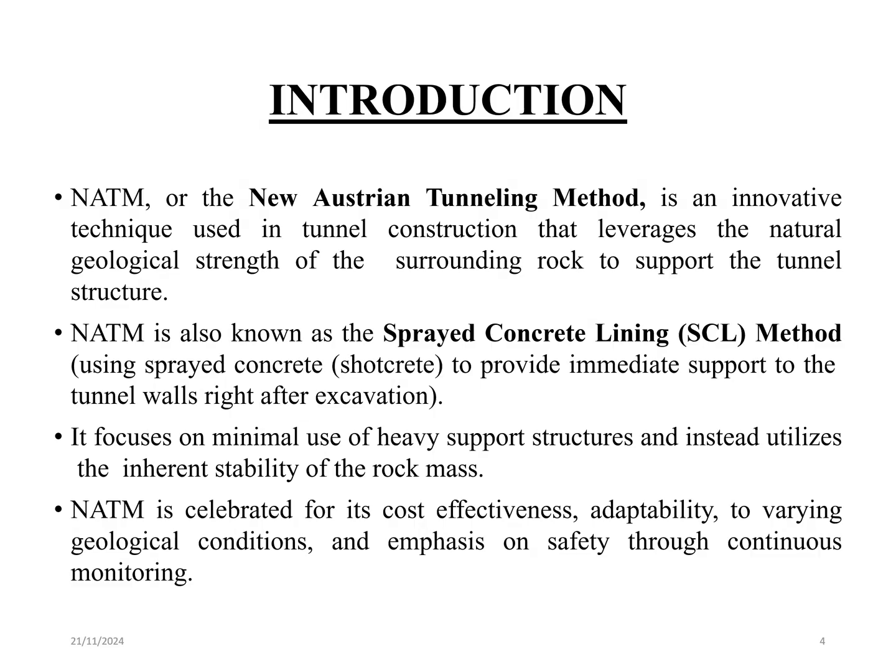Introduction to NATM. NATM is an innovative tunneling technique that leverages the natural geological strength of the surrounding rock to support the tunnel structure. It is also known as the sprayed concrete lining, in short SCL, method, which uses sprayed concrete, shotcrete, to provide immediate support to the tunnel walls right after excavation. This method focuses on minimum use of heavy support structures and instead utilizes the inherent stability of the rock mass.